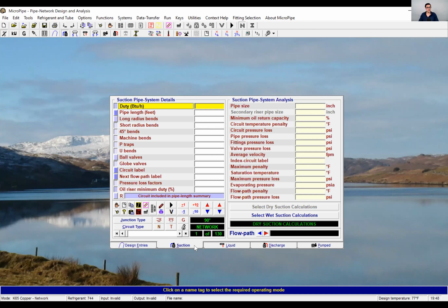Here in North America, liquid lines, Trevor, are quite important. For liquid lines, I try to target a maximum velocity, certainly at the fixtures, of 1 meter per second, because once you hit an AKV, assuming it's an electronic expansion valve, you don't want to be above 1 meter per second. You could suffer from liquid hammer.